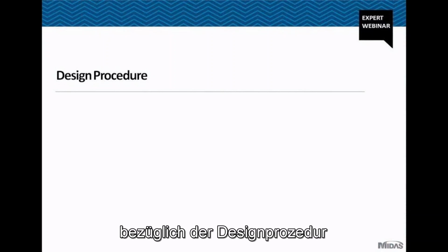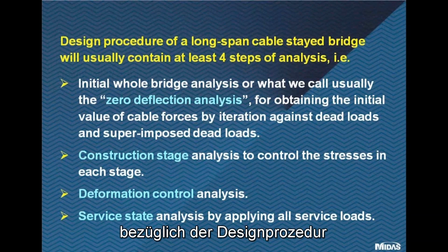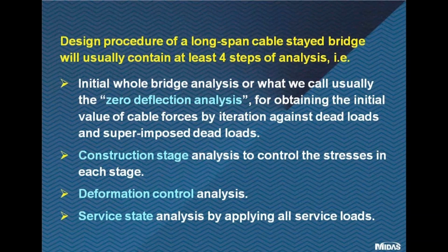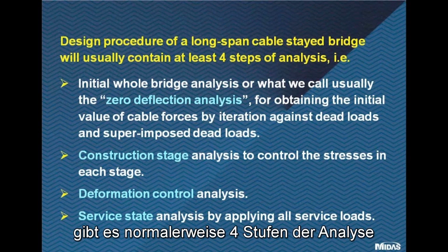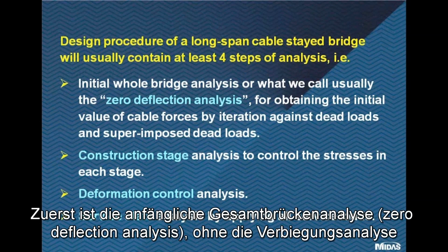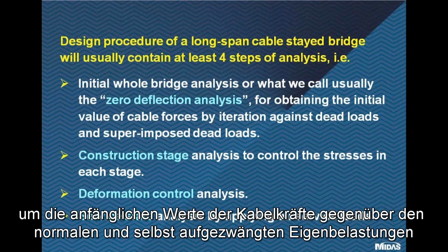Regarding the design procedure, particularly for a long span bridge, it will usually contain at least 4 steps of analysis. First step is the initial whole bridge analysis, or what we usually call the zero deflection analysis, for obtaining the initial value of cable forces by iteration against dead loads and superimposed dead loads.